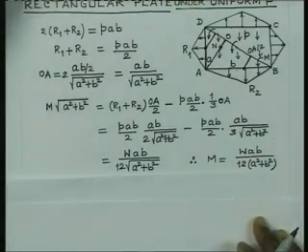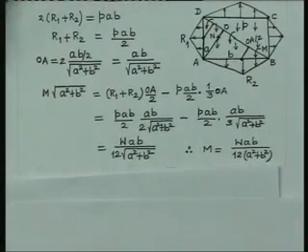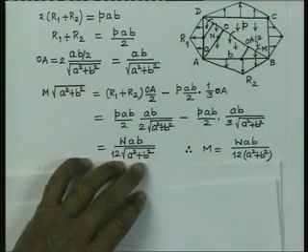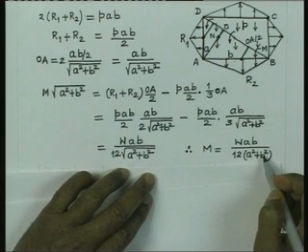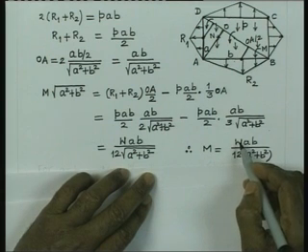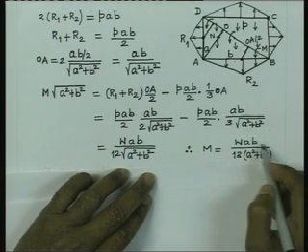So, that is the moment per unit length. Obviously you see that the unit is also balanced, because this is going to give us meter square, which cancels with meter square, and we can write this as Newton meter per meter.